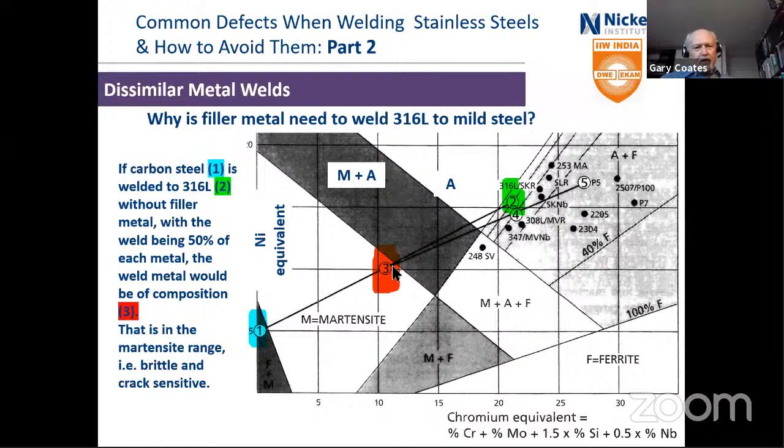It's going to be brittle. It's going to be very crack sensitive. You don't want to do it. So that's why you would never weld this combination without filler metal.